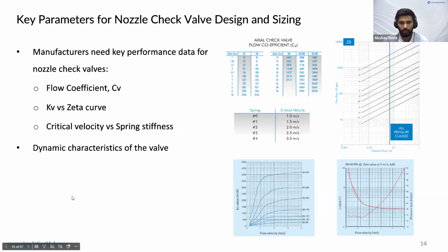So we have been through a lot of definitions and terminologies, and we had a look at what check valves are, what a nozzle check valve is, what slam and non-slam are, why check valves, and what the key parameters are that are required in designing check valves. We saw why the nozzle check valve is better than the other two designs.